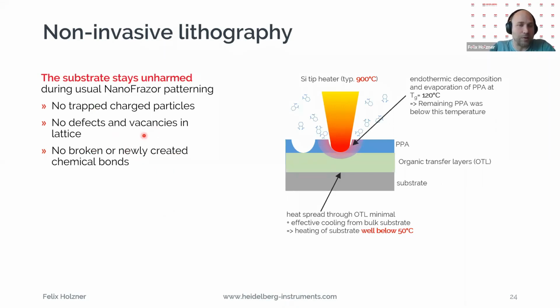For many applications, that's not a problem, but there are some things where this is an issue. And we actually don't damage the substrate below. I mean, we have people who are afraid that with our hot tip, you would actually damage a sensitive material here. But also in a separate webinar, we will cover this whole topic of how hot it actually gets here, what's the temperature here, and what's the temperature here where your sensitive material might be. And you will see this is not heating up, maybe not even to 10 degrees or so. That's not heating up here. It's only heating up at the resist on top.